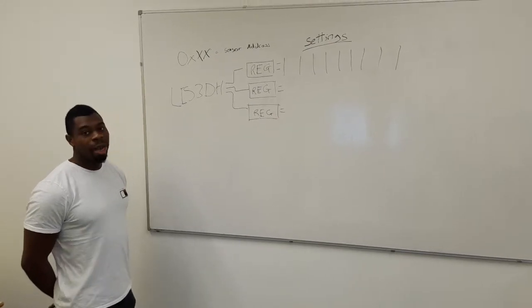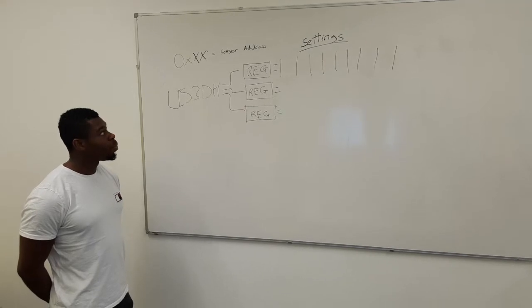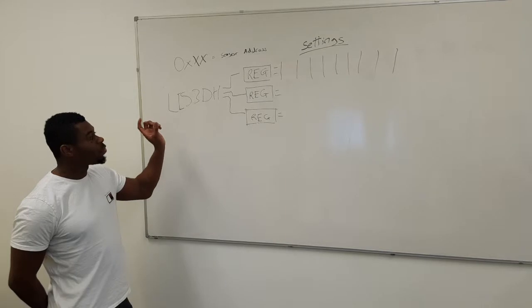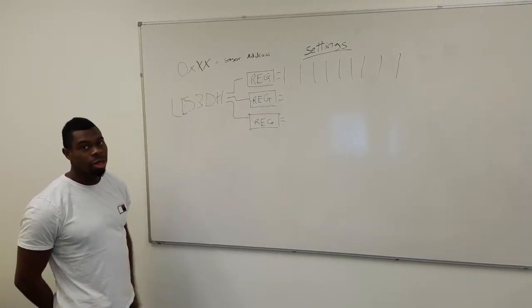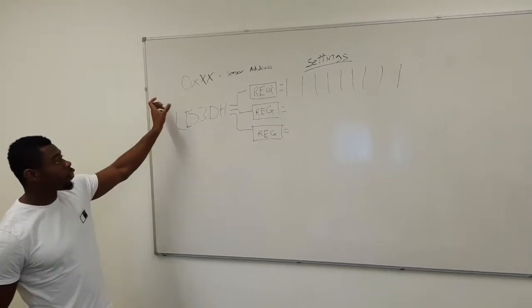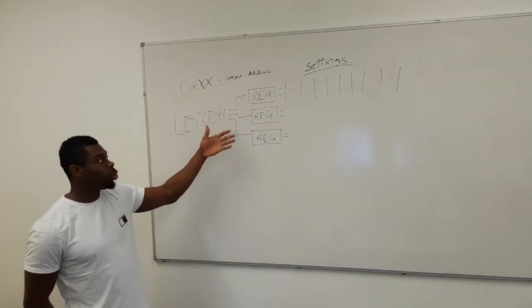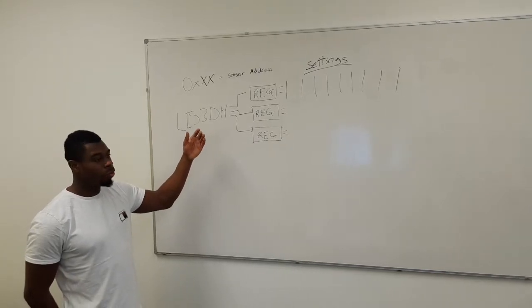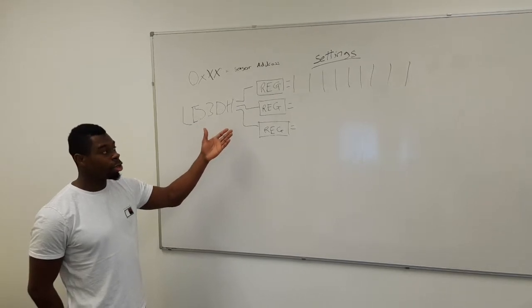Once we've been able to connect to our particular sensor, the accelerometer, what we then have to do is interact with the different registers associated with that, which allows us to perform particular functions that we wanted to do. For instance, once we've selected the address, we can then pick a register that will do a particular function, for instance, enable the XYZ values, or deciding what type of G-force range we want to instantiate.